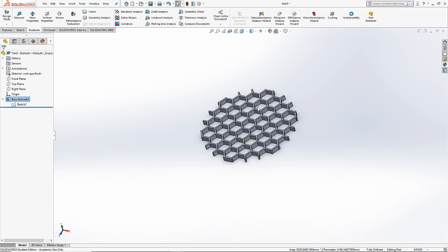My point is, you can create patterns within a sketch. You can create patterns of features. They are two different things. They are useful or not useful in certain circumstances. The big advantage of creating a pattern within a sketch is that you can reference the sketch. You can apply relations, you can apply dimensions to it in the same way that you could any other sketch entity. You can't do that in the same way with a pattern of features.